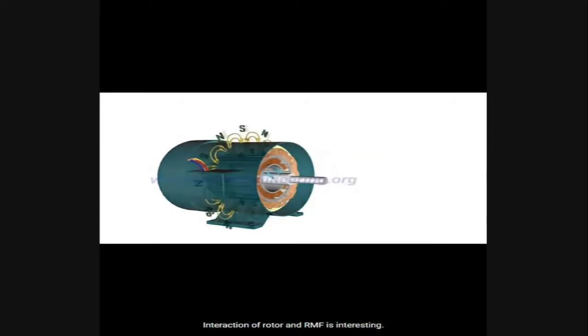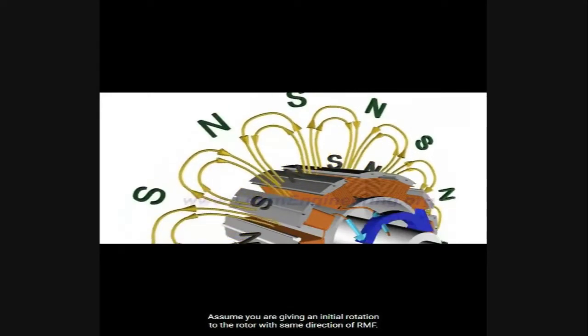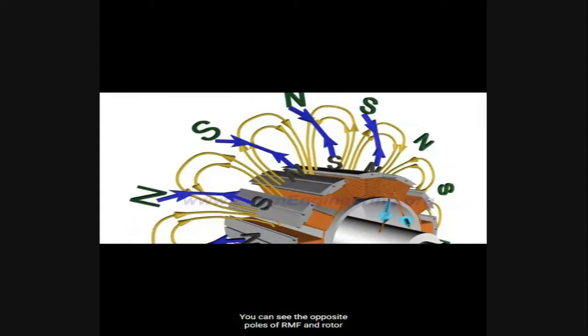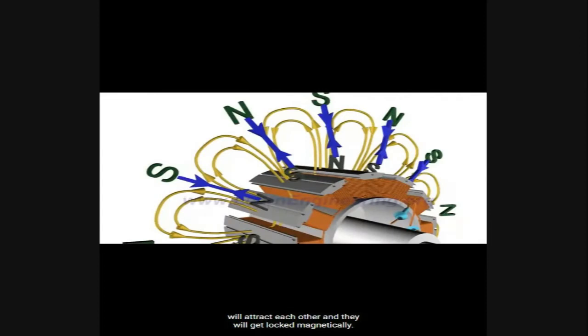The interaction of rotor and RMF is interesting. Assume you are giving an initial rotation to the rotor in the same direction as the RMF. You can see that opposite poles of the RMF and rotor will attract each other, and they will get locked magnetically.